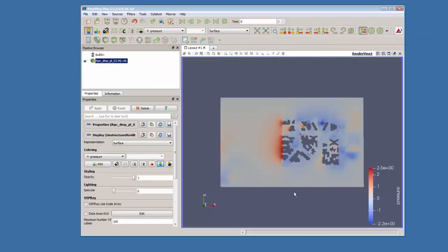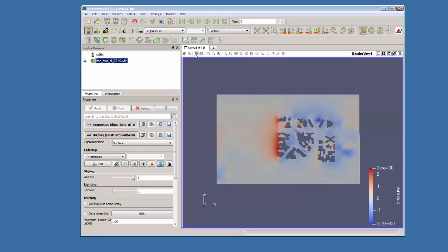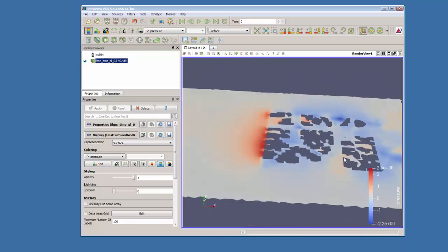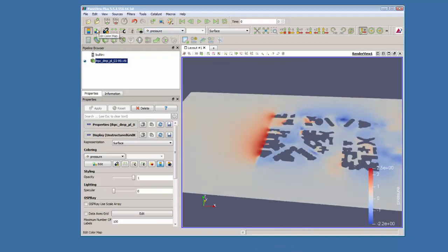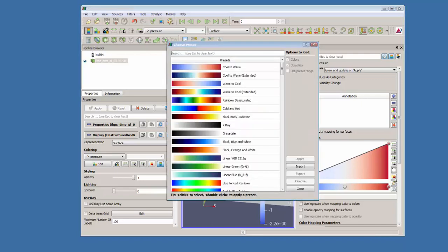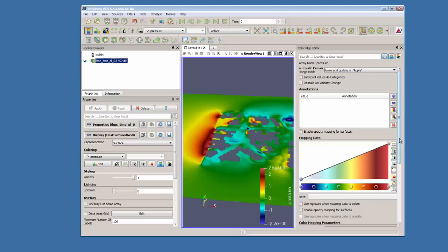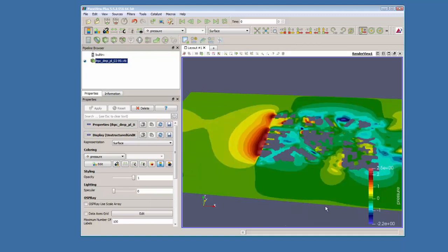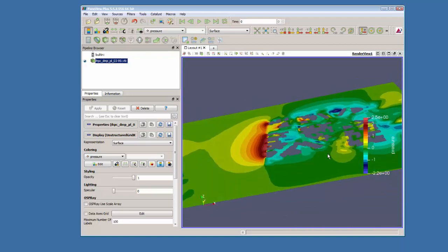First, starting ParaView, we can load some data, in this case a section plane that's got some contour colors representing pressure. Position that in 3D. We can change the default color map, just pick one of the standard favorites here. Pick one that isn't default, and then we can go down to the bottom of the color map menu and we can change the number of discrete layers to 24 rather than a continuous level, and we have a reasonable scene that we can position, set the legend, and create a small visualization.